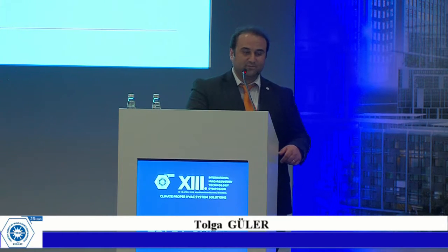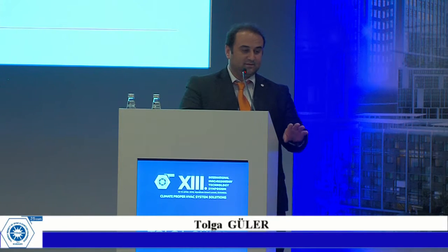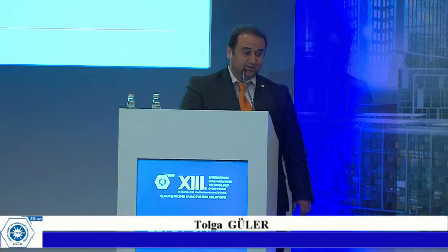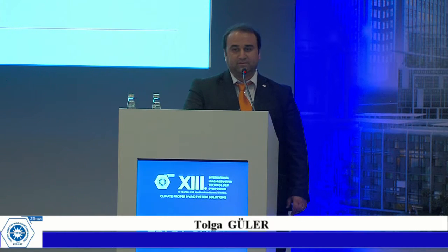And the second model is the gap model, and it's the same. Either we can use the original manufacturer's CAD model or the reverse engineered CAD model in the simulation. But there's a difference for cells: there's only one row of gap cells between the neighboring fins in the gap model. And the last one is the coil approximation by porous modeling. Coil geometry is non-existent here.